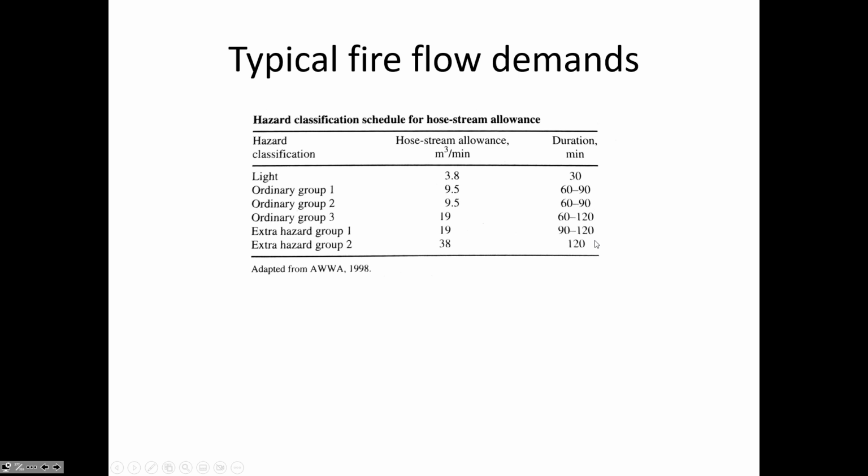So it may mean that you have to have really large pumps available to generate enough pressure, because it's unlikely that you'd be able to have so much elevated storage as that. So the pumps would have to be much, much larger than the pumps that need to be in place just for the ordinary residential demand.